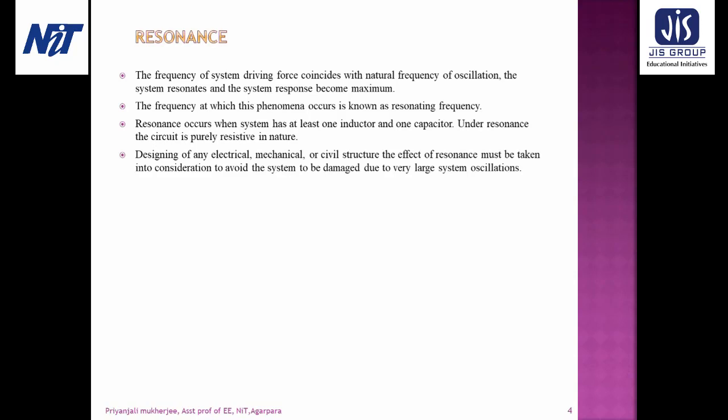Now, what is a resonance? Resonance is a very important property of a reactive AC circuit employed in a variety of applications. And any system having at least a pair of complex conjugate poles has a natural frequency of oscillation. If the frequency of the system driving force coincides with the natural frequency of oscillation, the system resonates and the system response becomes maximum. This phenomenon is known as the resonance, and the frequency at which this phenomenon occurs is known as the resonant frequency.